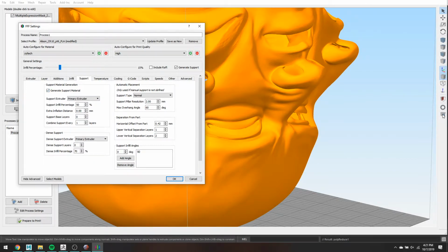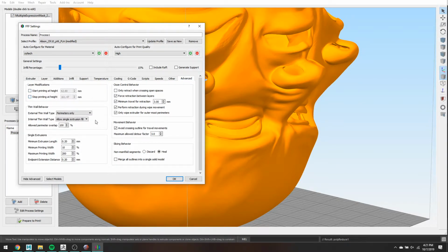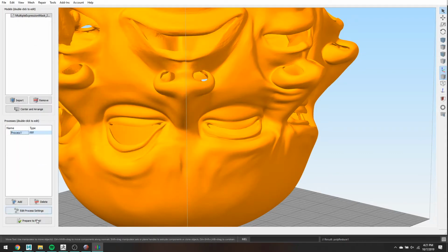So you can set up manual supports, which is like what I showed you with adding support. That'll pretty much override any other support settings that you have in your support tab, short of turning off supports. If you turn off supports in your support tab, it will not print any of your predefined supports. But if you have predefined supports, it's going to override any of the other settings in here because you've gone out of your way to define them. So in this case, I'm just going to turn off support material because I want a faster slice. Ignore that for now.